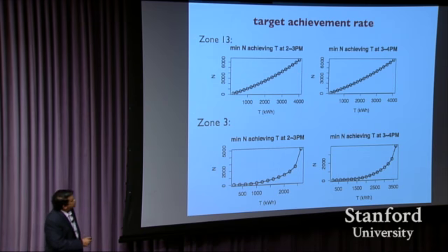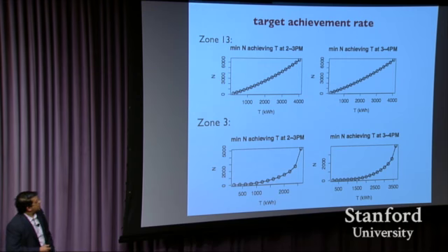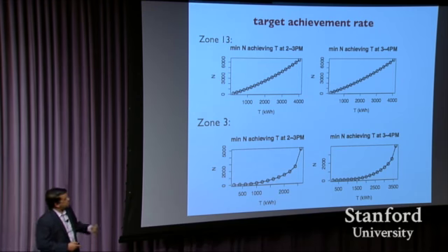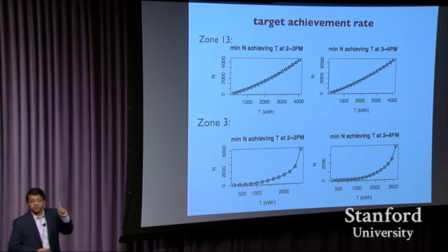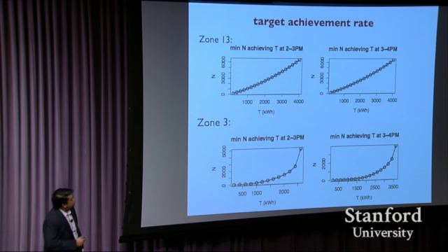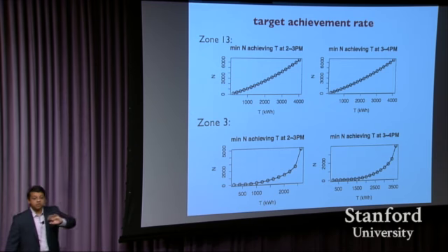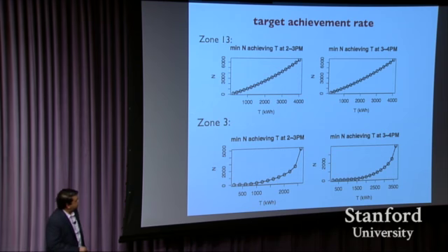It's kind of consistent from hour to hour. We fit a separate thermal model for each hour. And that allows me to estimate that initial number, which I showed, 250 megawatts per degree Fahrenheit, okay? Now, if I look at zone 3, which was the zone with no demand response potential, if you remember, right? So the average was 0. I still get something. I need a lot more customers to get my same 3 megawatts, but I still get something. So this algorithm shows that.